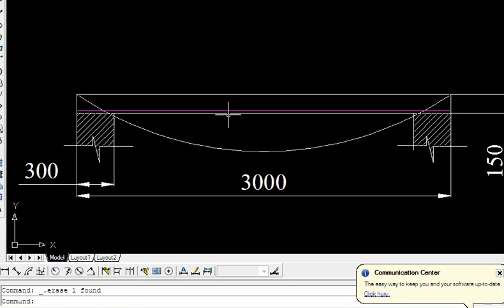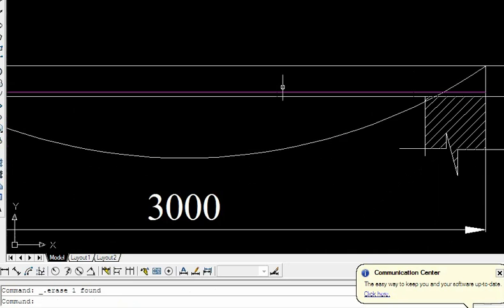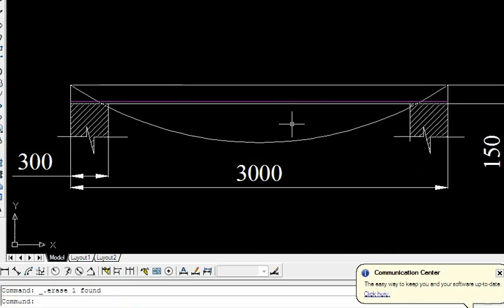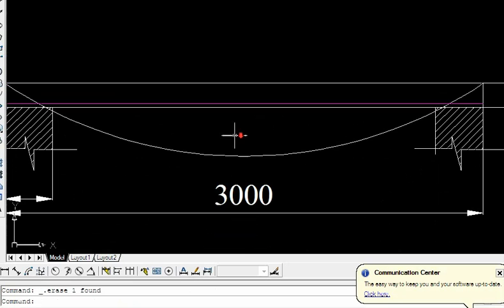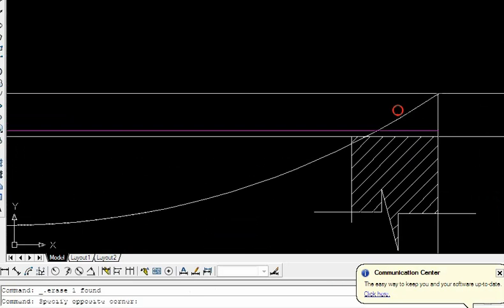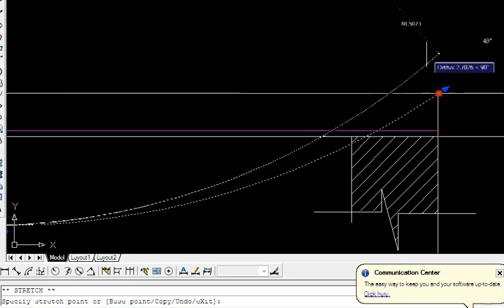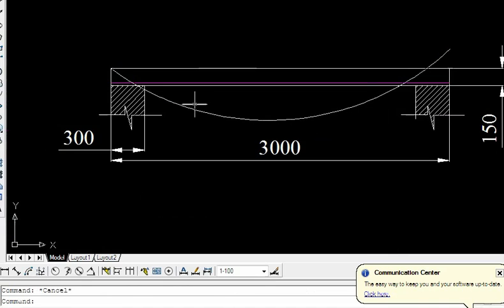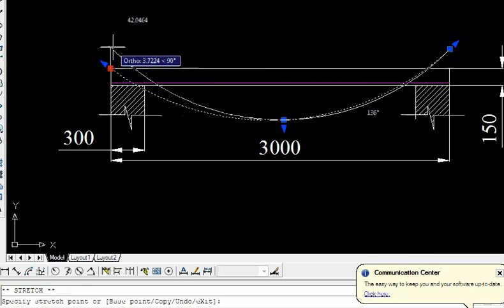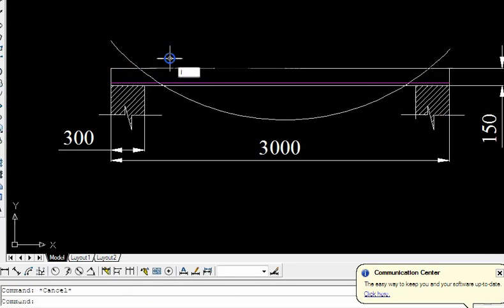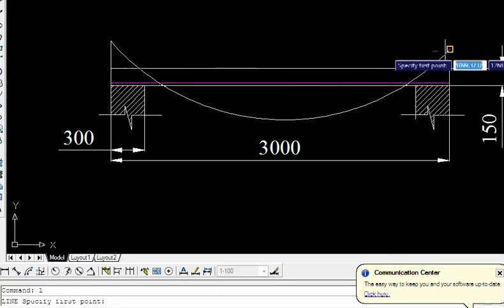This may lift the slab upward. So in order to make it contract, main bars are at supports, the moment will be negative at the top end. Let us show it here. This is a positive moment at midspan. At the same time, the negative moment will be there at the edges, like this. In regular practice, we get the bending moment diagram in this fashion. So negative moment at the end spans and positive moment at the midspan.